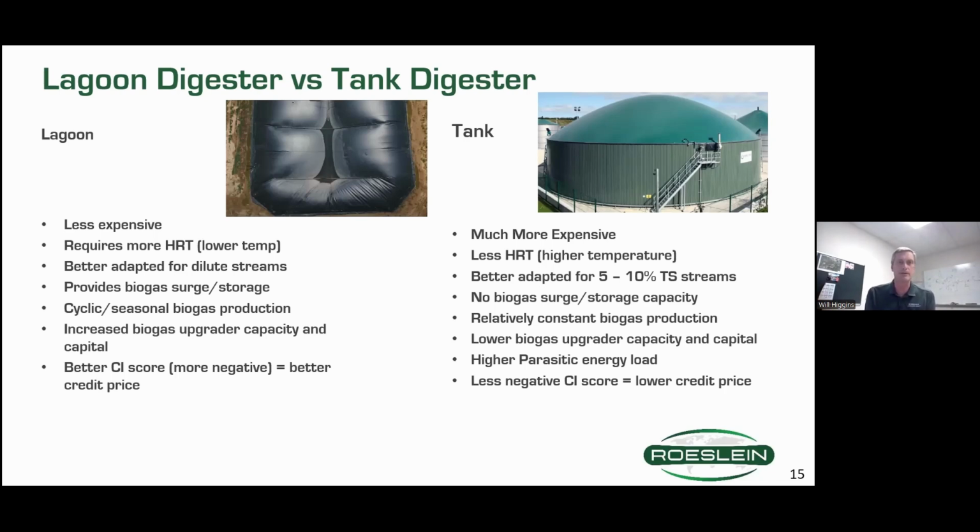You can sort of see a picture here. We'll put some weighted piping on top to help it inflate properly. And then with a tank digester, you've got much more cost. You've got a foundation, a solid tank, a heating system and mixers. So there's a much bigger capital investment to do a tank digester.